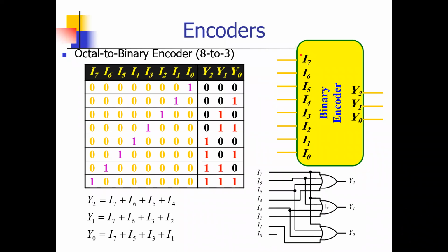You can see, we have OR gates, 3 outputs. I am giving the 8 inputs and 3 outputs, and this is the box. So in the box, we have OR gates in this form, inside the encoder box. I made an encoder box, but what is inside the box? Inside the box, we have OR gates in this connected form. Clear? The question will be drawing. A question can come in the drawing, but maybe I can show you this diagram and then we can ask what it is.